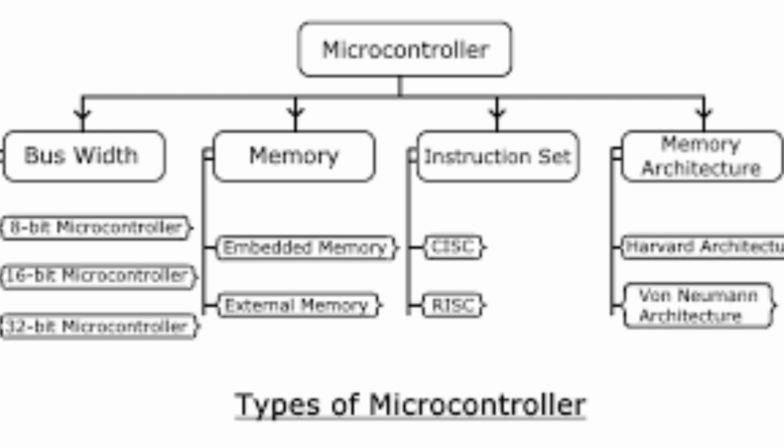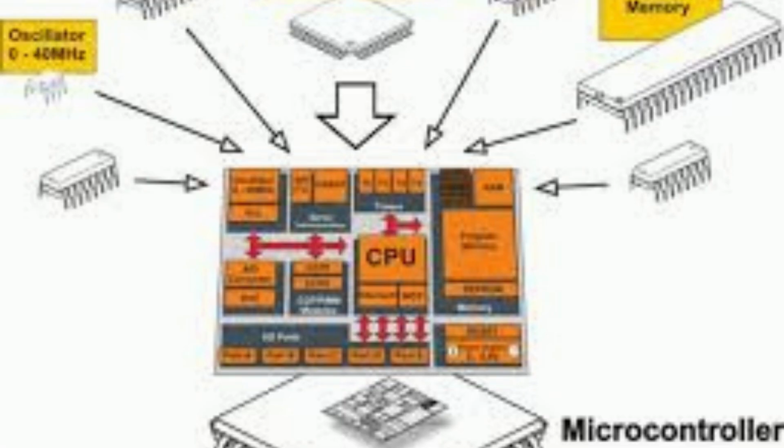Advantages of RISC architecture. Faster processing speed due to the simple instructions that can be executed quickly. Lower power consumption due to the reduced number of instructions required to perform a task. Improved performance as the simple instructions can be executed in parallel. Disadvantages of RISC architecture. Reduced functionality as the limited number of instructions may not be sufficient for all tasks. Increased complexity in software development as more instructions may be required to perform a task.